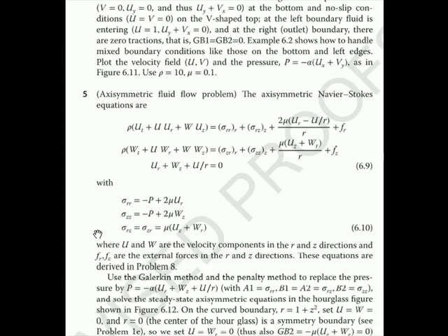Okay, we use the Galerkin method on both the penalty method and stream function approach. Collocation method works fine for the stream function approach, but that's only for 2D. For the penalty method, you can use collocation, and I do have a couple of problems, but it really doesn't work as well as the Galerkin method. And that means in 3 dimensions, where you have to use the penalty method and the collocation method, there are some difficulties, although there are a couple of problems in the text.